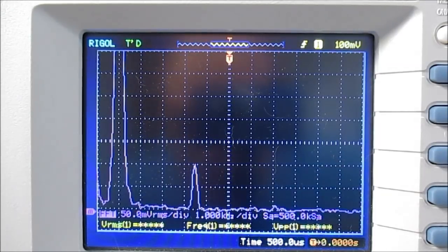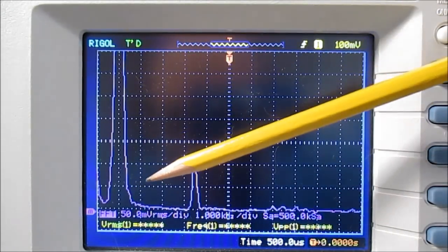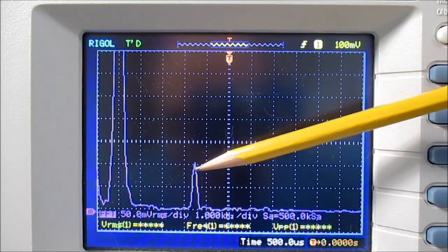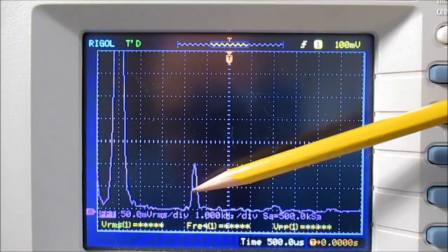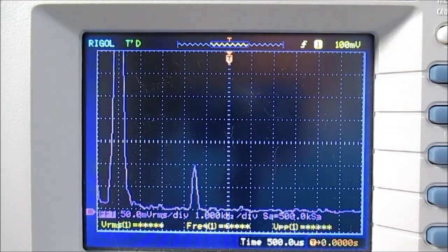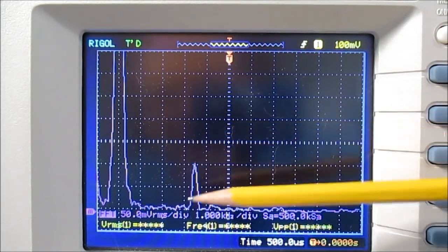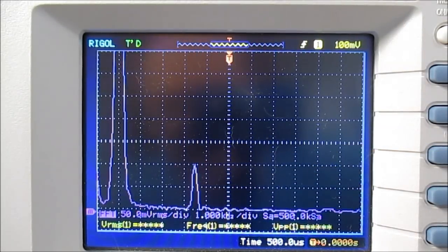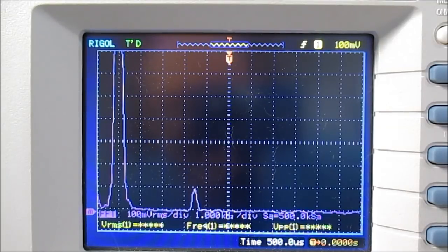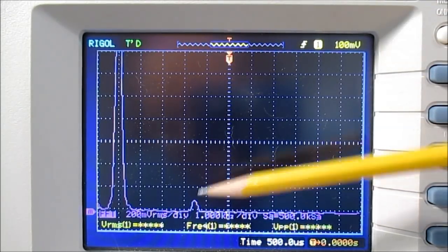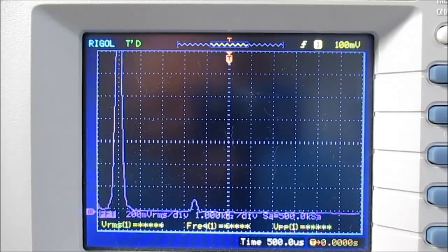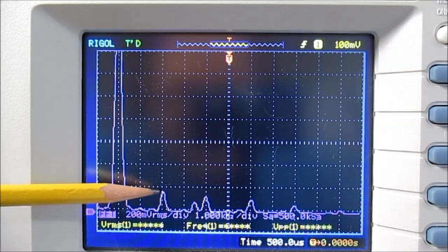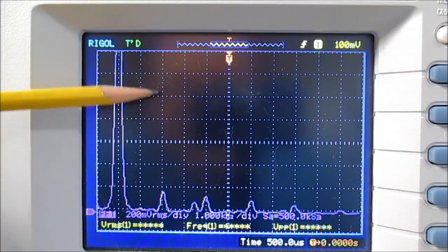Okay, as usual, we're in the spectrum analyzer mode on the scope. 1 kilohertz fundamental, 4.5 kilohertz 1% pilot signal. So I need to show 10% on here, and this is showing 2 graticules, so I need to turn it down, this 1%. So now it's at 1/2 of a graticule, so I can crank the amp into clipping. So we need, that'd be 2, 4, 6, 8, 10%.